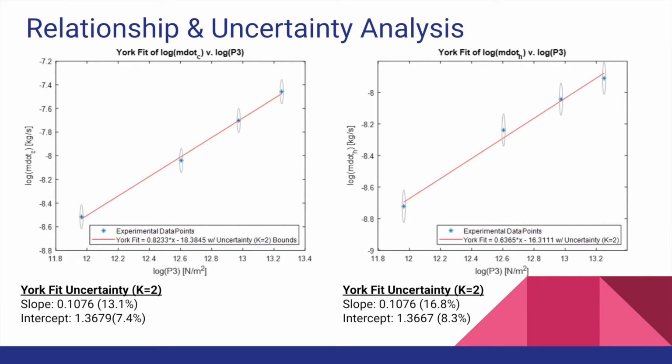This is because as we use more sensors to collect data and calculate a value, the error propagation causes a higher uncertainty. In this case, the calculation for mass flow rate used both an ambient pressure gauge, thermocouples, and volumetric flow sensors. If we had more accurate and precise sensors, we could have a higher degree of confidence in our answers for these calculated values.